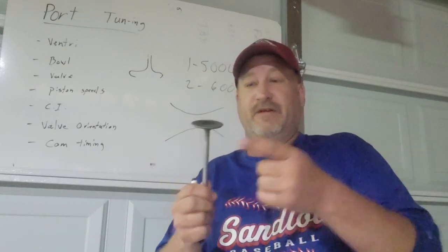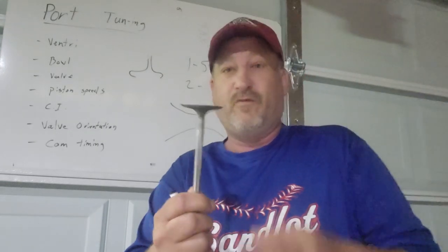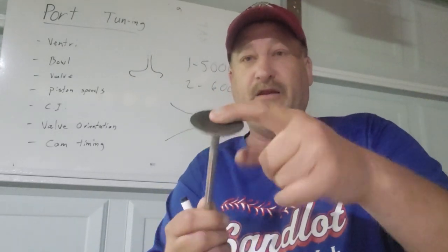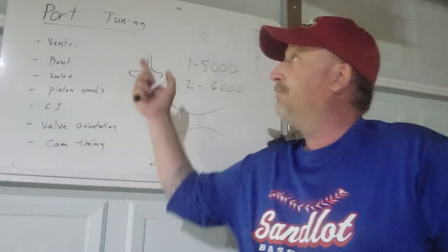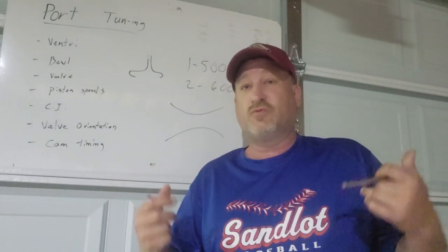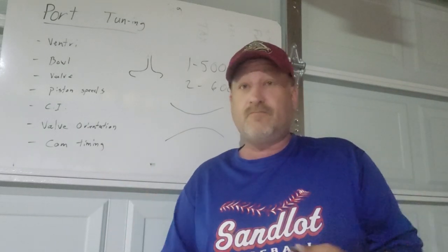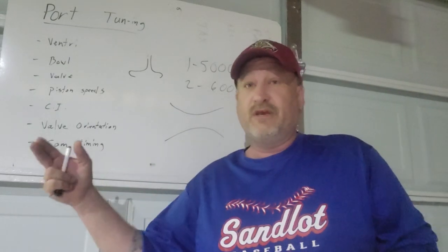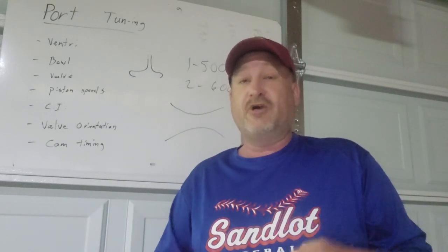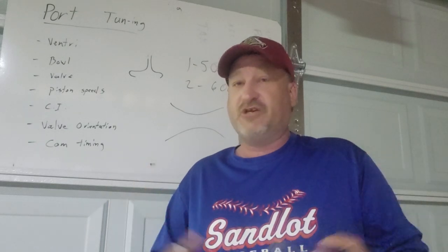So even the valve, not only the valve diameter, but the valve design itself, whether it be the nail head or the tulip design and the cupping of the valve, was part of the port tuning of where within the RPM range the engines were designed to be operated in a continuous motion. Not necessarily through the acceleration, but where the engines were held at RPM. So normally cruising speeds of where the engine is supposed to be most efficient.